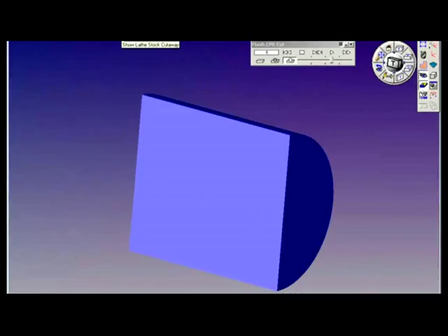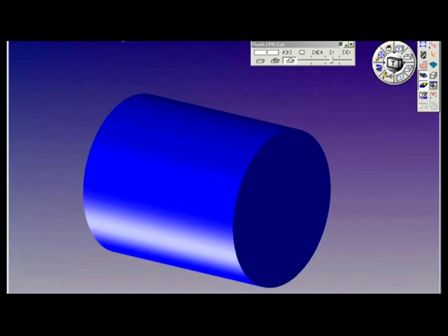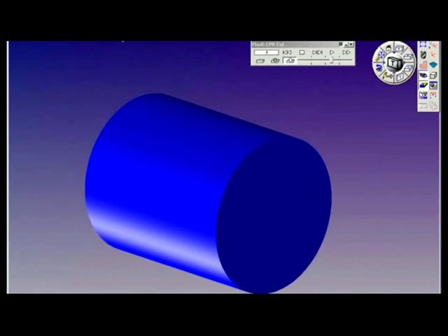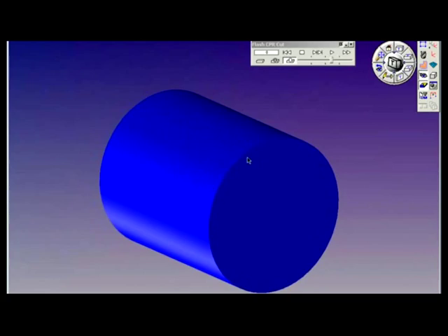Another click on this tile gives us a half view of the stock, and this is nice if you're doing machining from a lower turret on a NTM situation and you want to change the view of the rendered stock and see it cut from the bottom. You can go to half view or full view, which is commonly used when doing mill turn applications or NTM, and you have milling or cross drilling on the OD of the part that needs to be viewed in this selection. Turn off rendering.